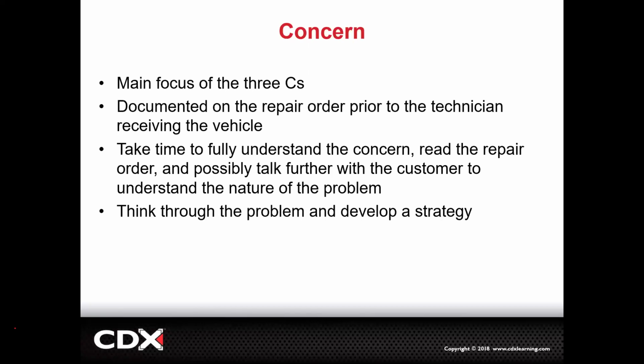I jumped in the Silverado and I noticed a couple details. I'll come back to those. And I thought, this AC feels cold to me. It's colder than my truck. I could have just said, nah, your AC is good, ship it, right? I could have. But to be thorough, I said the concern is the AC doesn't blow cold. I actually measured the temperature.